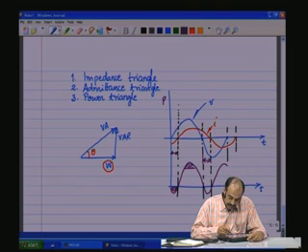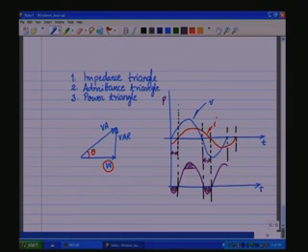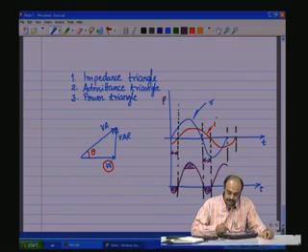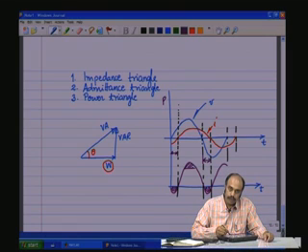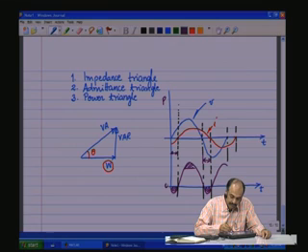So, this much amount of extra power, extra VA, is drawn from the mains, which gets put back in the following cycle into the mains, which is indicated by the negative power, which means the power is flowing back to the source. This is the power which is put back into the source, and that is the implication of negative power.